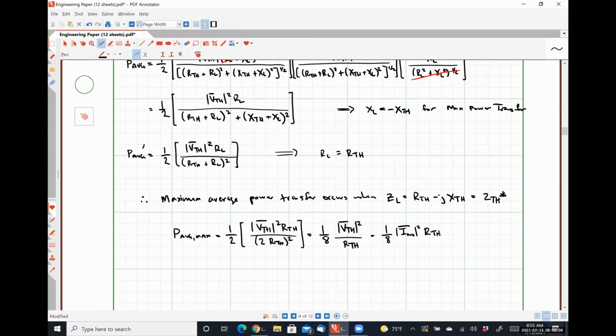All right, and then applying this is just like applying the maximum power transfer theorem that we did back in circuits 1. So I feel like going through examples is kind of redundant at this point. If you can express your circuit of interest as its Thevenin equivalent, you've done all the legwork to be able to determine the maximum average power transfer.